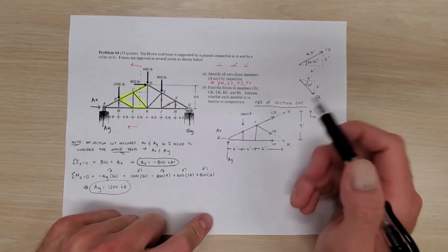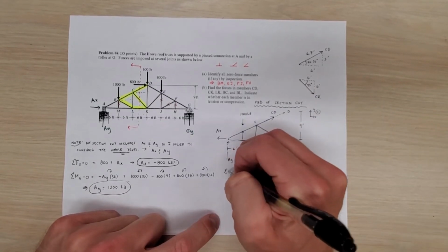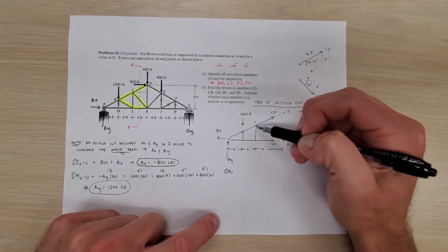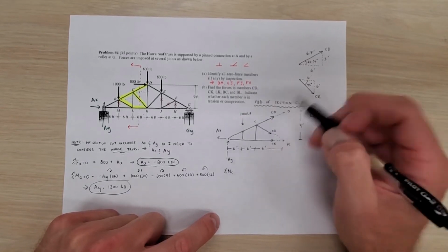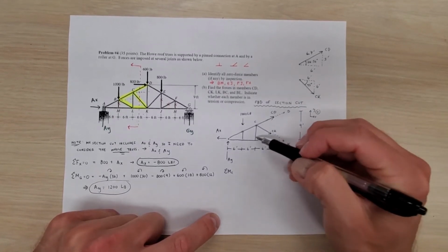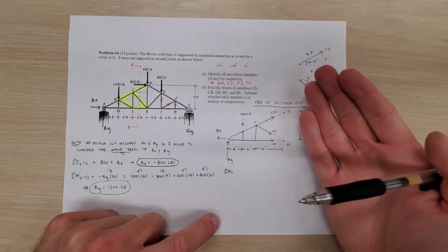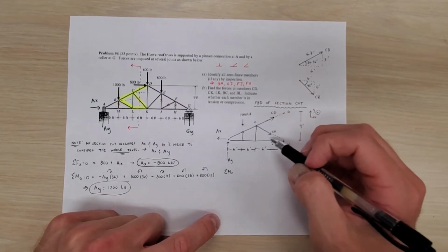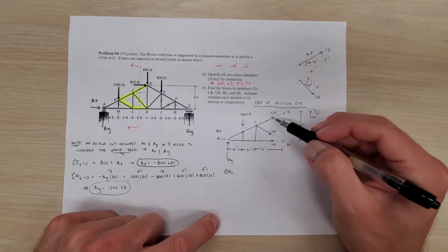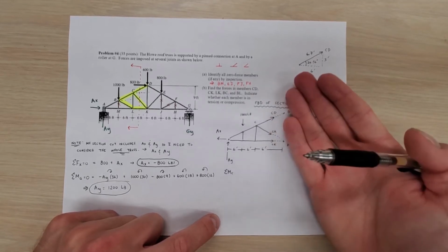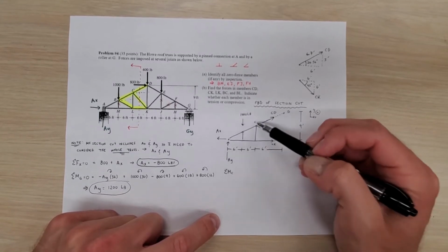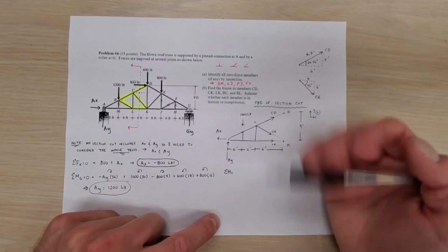So what I did when I solved this problem was I first took the sum of the moments about point C. So by taking the sum of the moments about this point C right here, I'm getting rid of CD and CK, and I'm solving very quickly for LK. The reason I'm doing this is because LK has only an X component, so it's going to be very easy to plug this into my equation, whereas if I started with the sum of the moments about K, I'd have to factor in all of the X and Y components of CD, and that just seems like a little bit more work. So let me write out the equation for the sum of the moments about point C, which is this point right here, and you'll see what I set up.